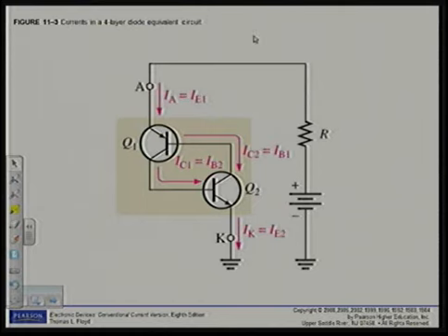Right, there you can see the currents flowing. At low bias levels, there is very little anode current, thus it is in the off state or in the forward blocking region. Then the important part, as we've seen from the characteristic curve as well, which is discussed on page 555, is the forward breakover voltage.